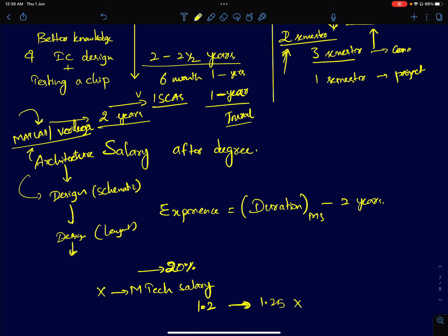Then usually we also do the packaging, in the sense we give suggestions on what kind of packaging you need. Whether it's QFN packaging, or a different packaging, or a BGA packaging. Typically you don't have much freedom. Whatever the lab generally does, you should do it, unless you're doing a very high frequency design, then you choose a different packaging.